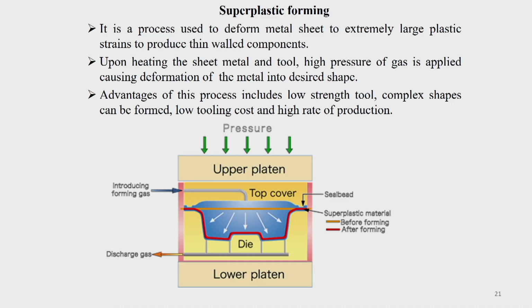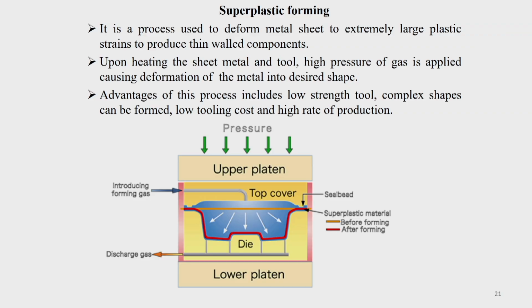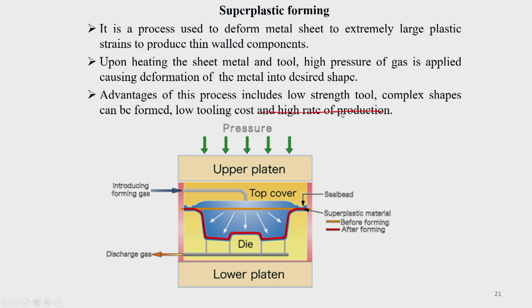By this process you can get very thin walled components with very high accuracy and good surface finish. The advantages of this process are low strength tools, complex shapes that can be formed, and low tooling cost. The rate of production is not that high, but the other things are fine. You can get very complex, highly intricate shapes, and the cost is not very high.